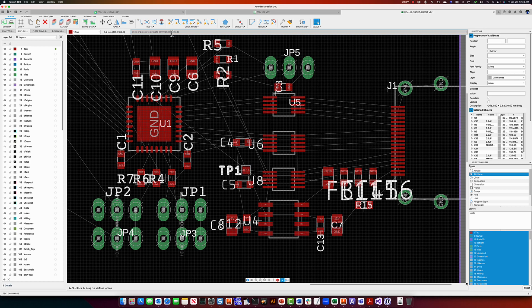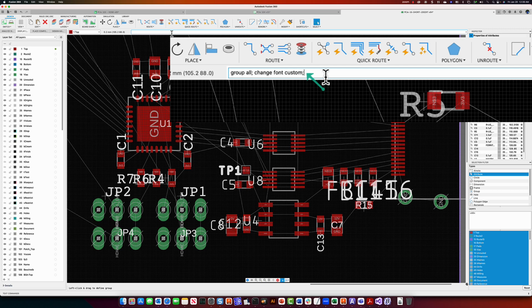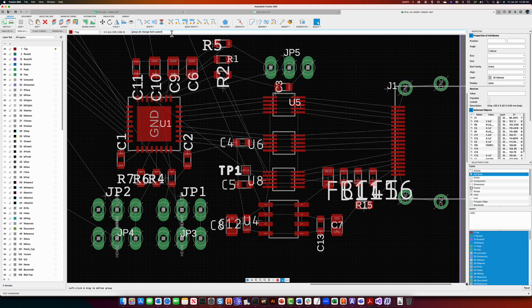Now, when I type that in at the command line and I hit enter, you would expect, well, something to happen to all objects. But that's not actually how that command works, because the all objects is applied from the right mouse. In this case, the semicolon is just terminating that, but I didn't have anything selected to begin with.